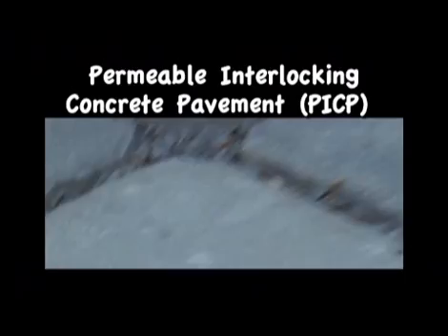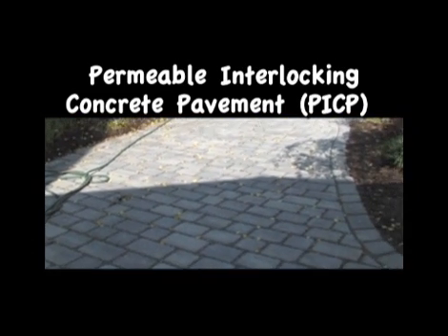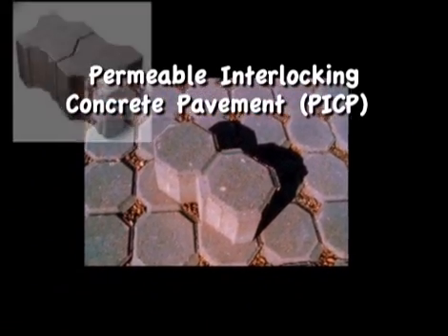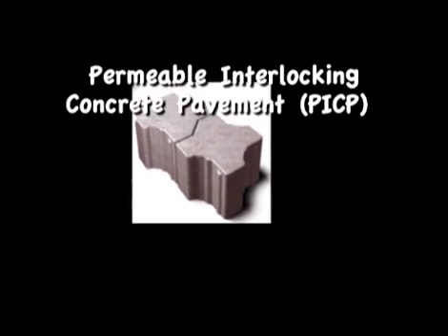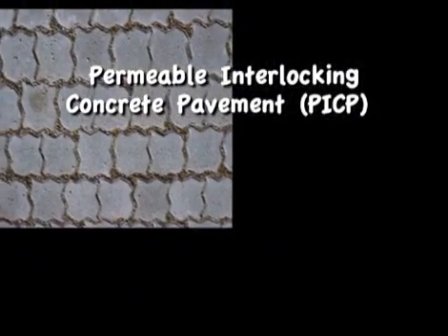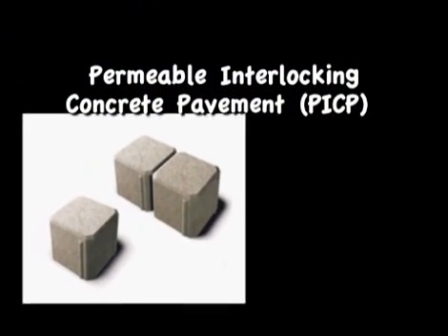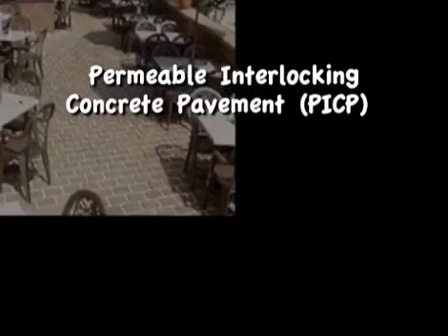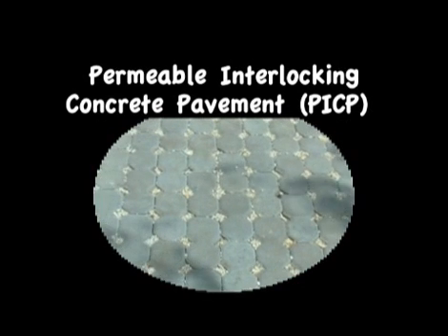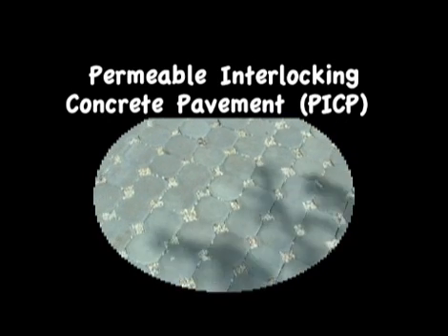A more sophisticated form of permeable paver is the Permeable Interlocking Concrete Pavement, or PICP. PICP comes in many shapes and colors and are designed for everything from parking lots and driveways to walkways and nature trails. PICP is comprised of a layer of durable concrete pavers separated by joints filled with small stones. The joints are interlocking shapes that vary from simple notches to built-in concrete joint spacers. The blocks themselves are actually impervious. However, the joints allow for water infiltration.